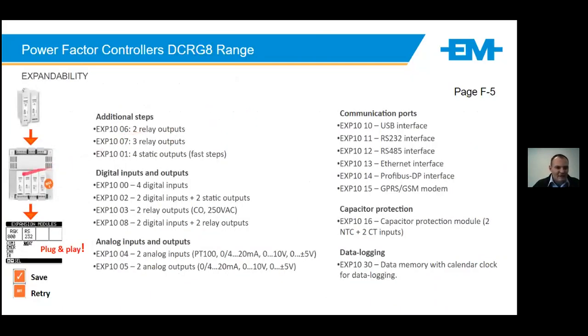Expandability, again, 4 modules, max. This allows for additional relay steps, for standard contact switching, expansion for static switching, so for fast switching via thyristors, digital inputs, digital outputs, relay outputs, analogs.